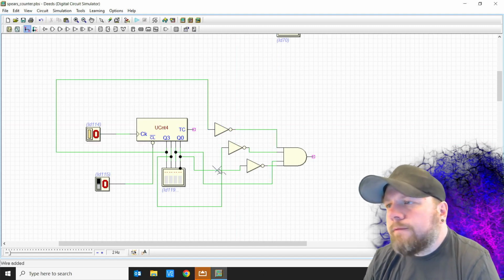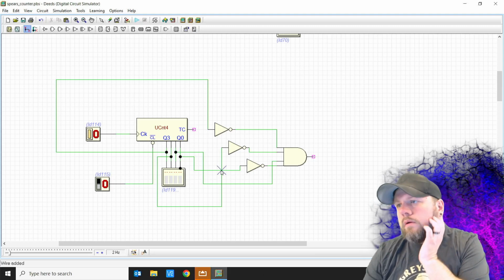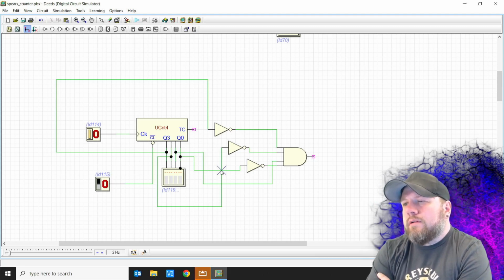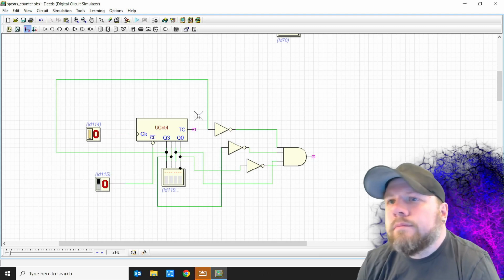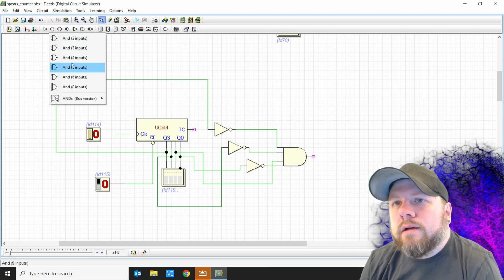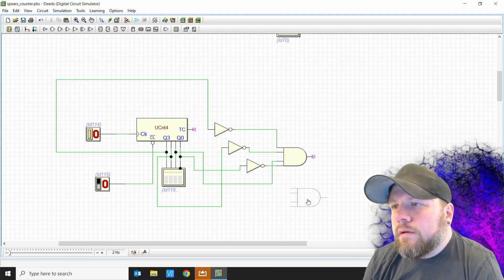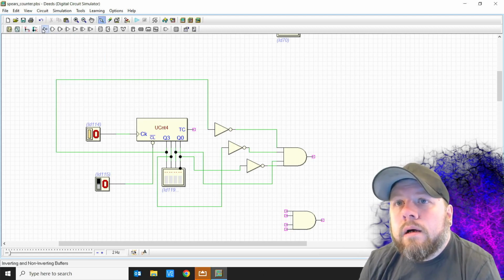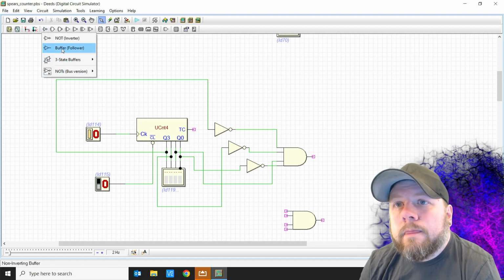All right, and I said 5, which is 0 1 0 1. I want to do something with fewer inverters, so let's say 7, which would be 0 1 1 1. Does that sound all right? It could be any number that we want. We just make a decoder to work, and a 7 would be only one inverter.